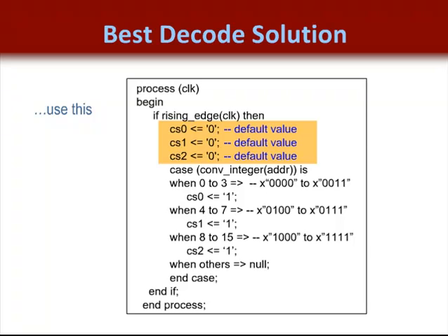This is an important basic HDL coding style to use whenever you build a combinatorial process. This helps you to avoid inferring latches, so to be sure you don't, use a default. Usually synthesis tools will warn you if you happen to forget the use of the default statement.